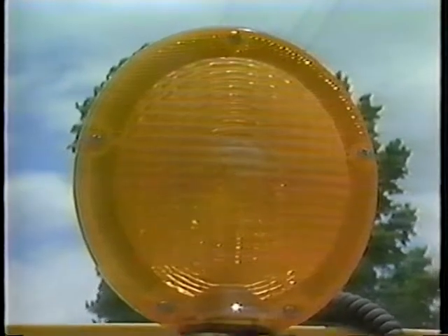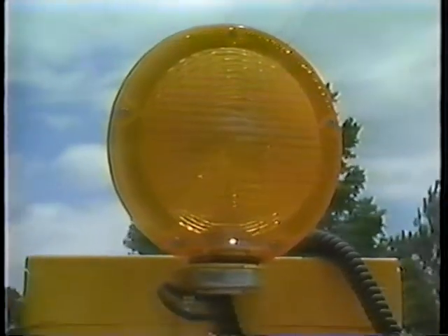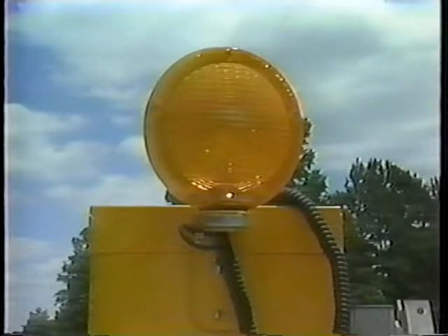High-intensity lights, Type B, are used on advanced warning signs day and night and with high-level assemblies. Steady burn lights, Type C, are used on a series of channelizing devices or on barriers which either form the taper to close a lane or shoulder or to keep a section of lane or shoulder closed, and are also used on the channelizing devices beside the work area at night. Both Type A and Type C lights have photoelectric switches to activate them at night.